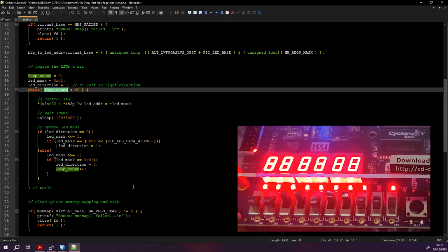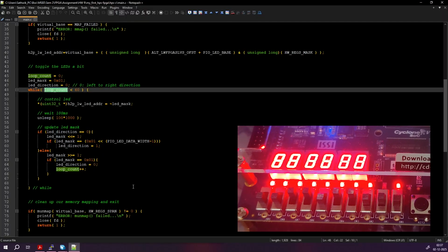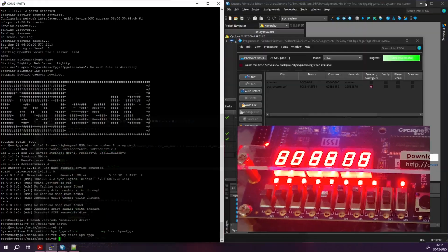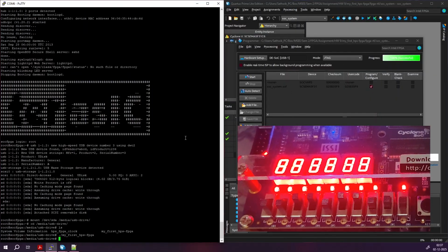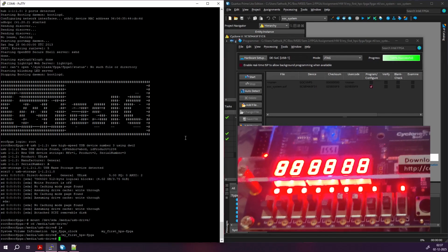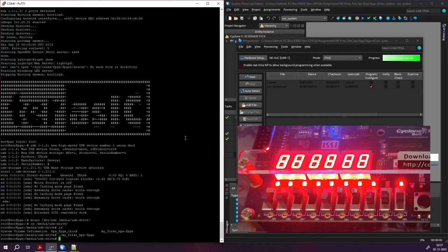But we can see that the configurable part is still reading the last data and updating the LED accordingly. Since the software terminated, the memory block is no longer being updated from the software. So the FPGA part is reading the last known value and performing the logic computation based on that.